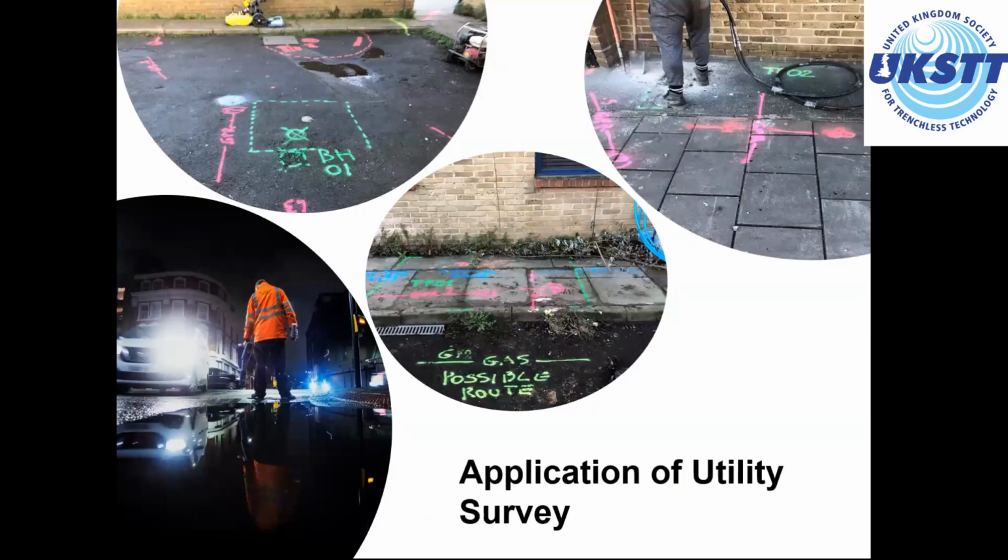The majority of projects that would require references to HSG 47 and PAS 128 are, for example, borehole locations. A 10-meter borehole needs to be installed, needs to be drilled within a public footpath. Plowman Craven, or any other survey company, will come along and carry out a plant avoidance survey. With a plant avoidance survey, there would be no specific deliverable. It would literally be a markup on the ground showing where all the anomalies or utility related features are, and the borehole would be positioned around them to avoid any damage.